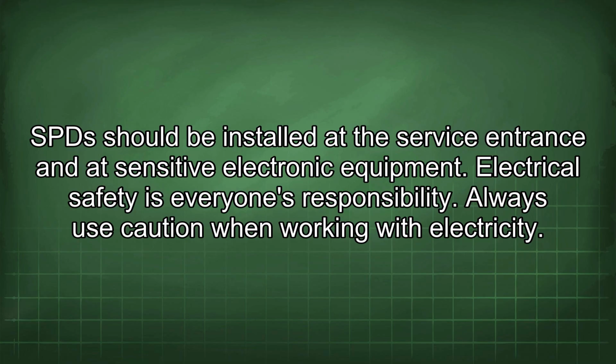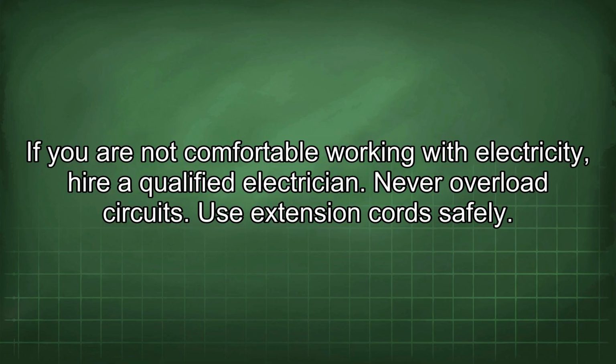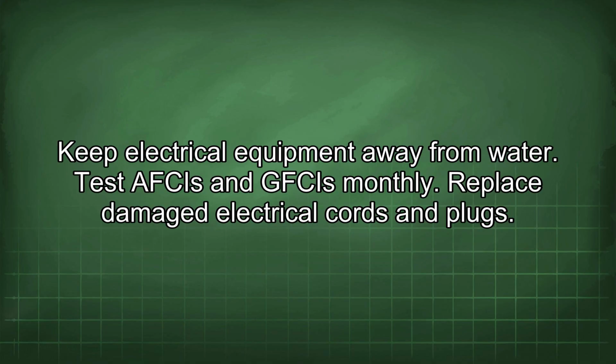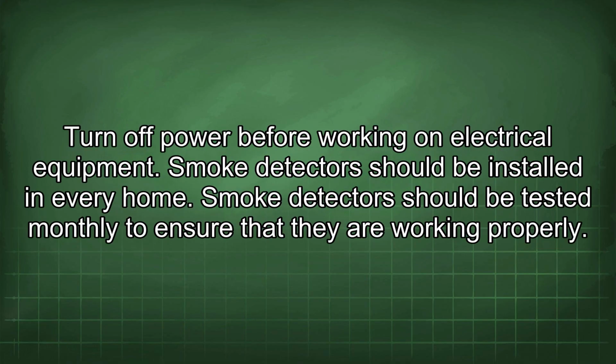Electrical safety is everyone's responsibility. Always use caution when working with electricity. If you are not comfortable working with electricity, hire a qualified electrician. Never overload circuits. Use extension cords safely. Keep electrical equipment away from water. Test AFCIs and GFCIs monthly. Replace damaged electrical cords and plugs. Turn off power before working on electrical equipment.